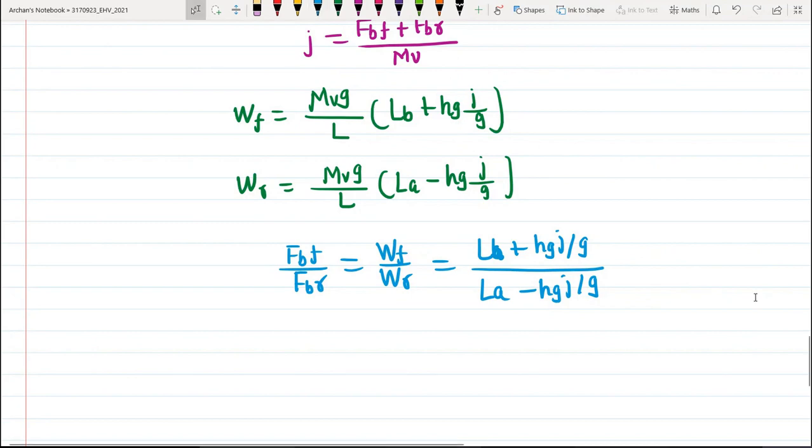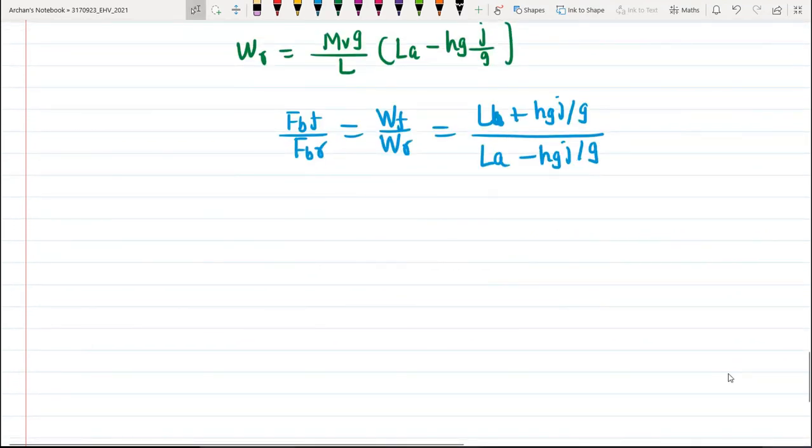While designing the vehicle, we need to take care of this, and let us call it beta. So beta will be equal to Fbf upon Fb. What is it? It is the actual braking force on the front and rear axles, designed to have a fixed linear proportion. This proportion is represented by the ratio of front axle braking force to the total braking force. Here Fb is the total braking force of the vehicle.